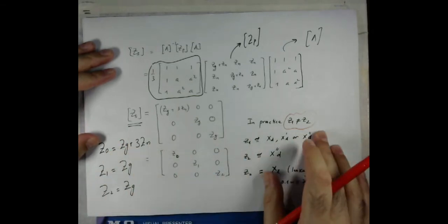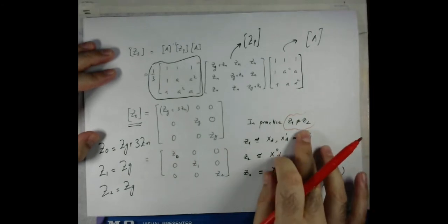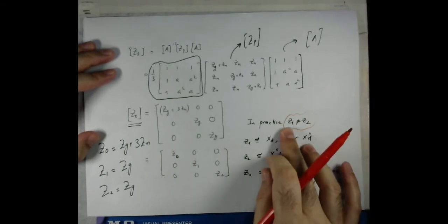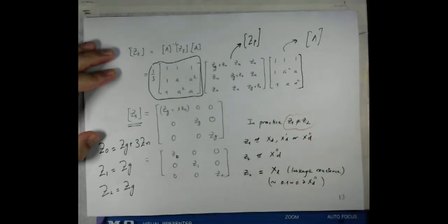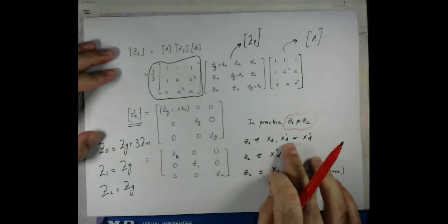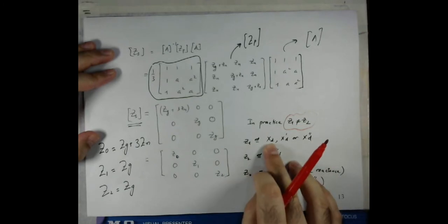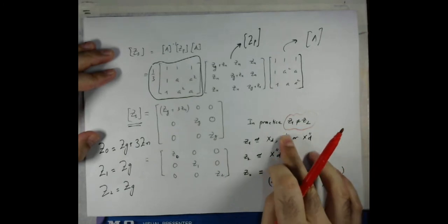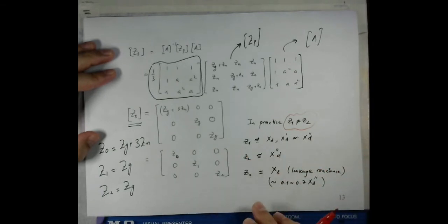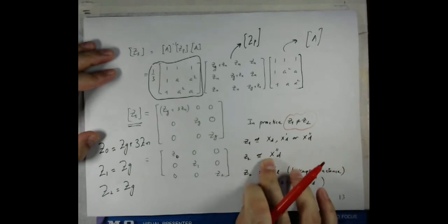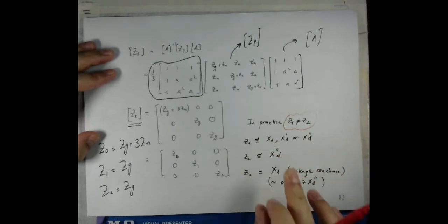However, in practice, this is not the case. Positive sequence impedance is not equal to the negative sequence impedance. Usually, the positive sequence impedance is taken as either the steady state inductive reactance, transient inductive reactance, or the subtransient inductive reactance. And Z2, the negative sequence impedance, is approximately taken as the subtransient inductive reactance.